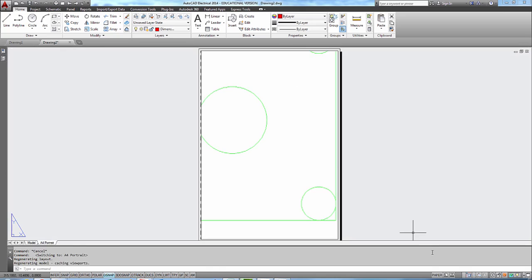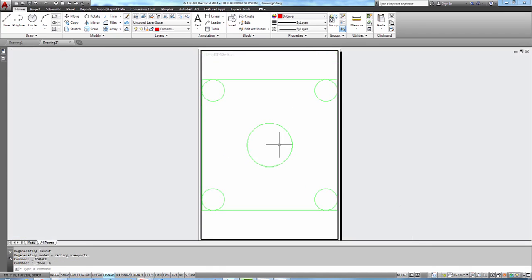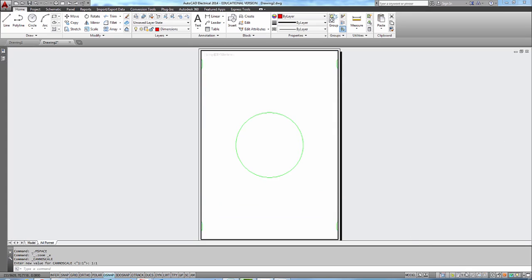So you double click, make sure you are in model space, double click the wheel, and if you choose scale 1:1, you can see it's not appropriate. So let's try now for a scale of 1:2, and that seems to be reasonable. So this now we can work with.